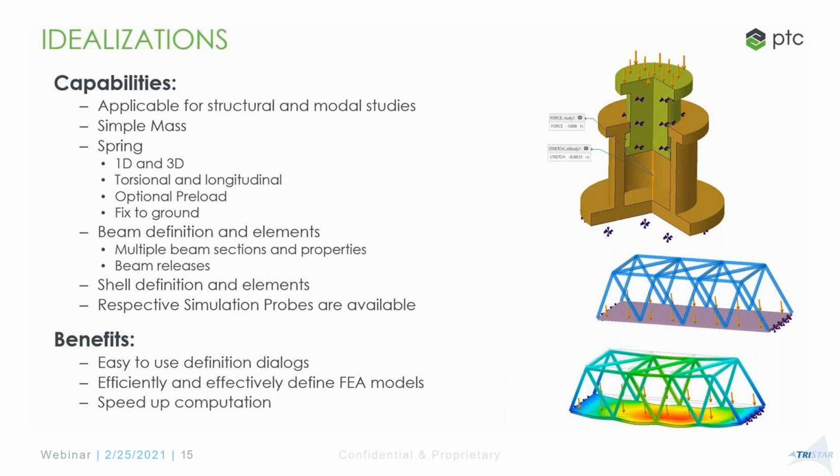They also support idealizations, and I'm sure all of you understand what idealizations are. They are nothing but mathematical approximations in any analysis model, right? Do you have to have the entire CAD geometry when analyzing it? Not necessarily, right? I may have a driving belt, or I might have a bushing, and the driving belt's job in my assembly is to just impart stiffness. So why should I be using the actual CAD geometry as a 3D mesh? I could just create a spring to mimic that particular driving belt, for example, right? So I may just use 1D or 3D spring elements inside of my assembly here.